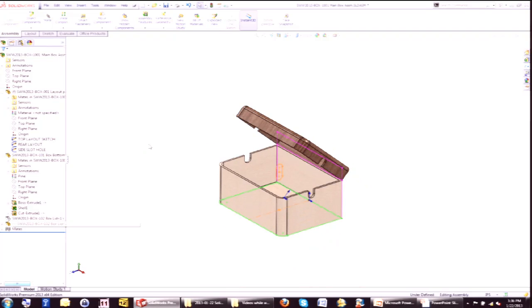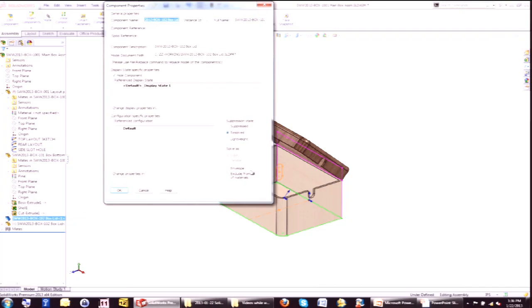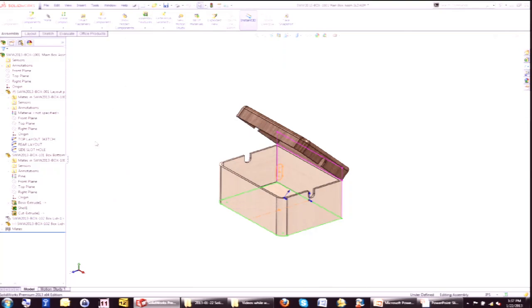Now, we're going to end up with multiple instances in our bill of materials, so what are we going to do? You know it, right? Right-click, exclude from BOM. So we go to this one that we hit here, we right-click, and then go to properties, and we can just say exclude from BOM, and then we won't end up with those multiple instances.